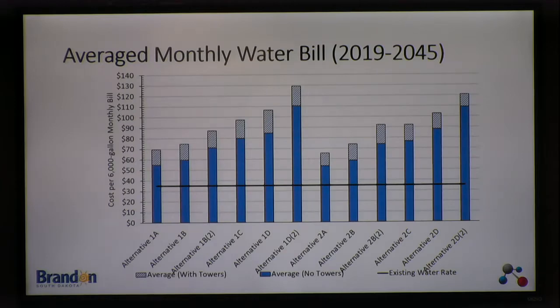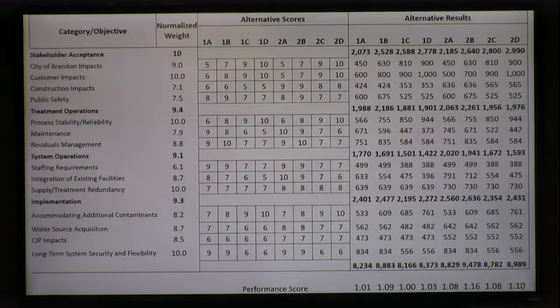Just to clarify, it's not a quarter of the water. It's a quarter of the water that's approaching the RO system. So it ends up being less than 25% of the water that's being treated, closer to like 10%, right? Okay, still that. Absolutely. As opposed to the 90% that we're wasting if you don't do it.